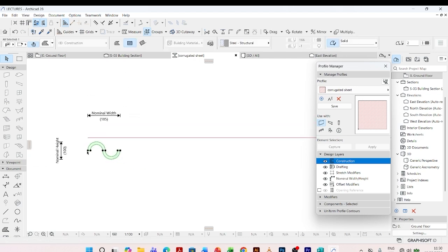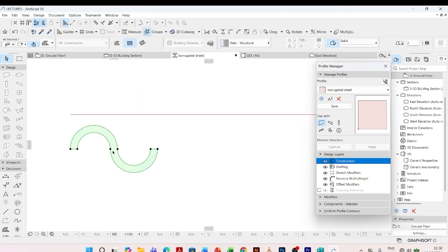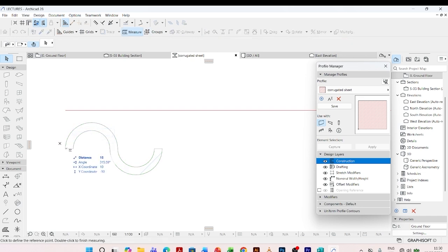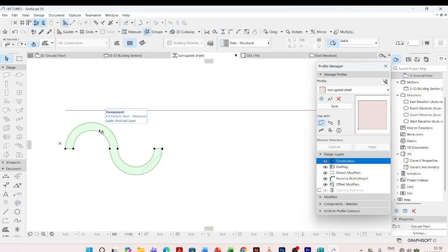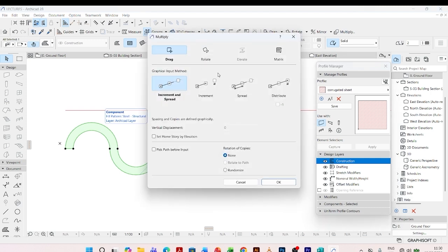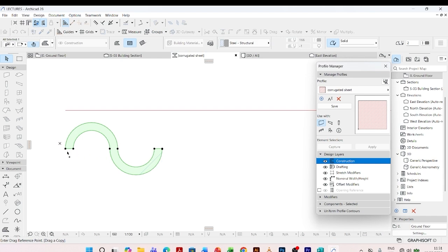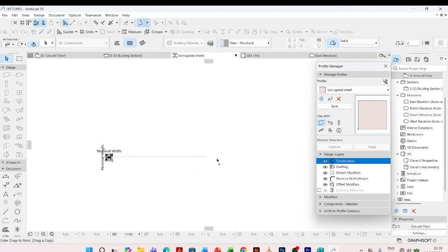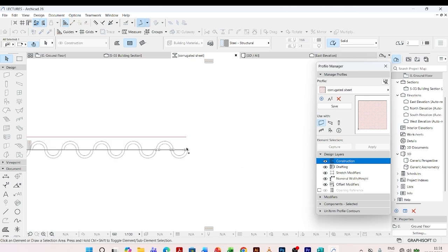So I'm going to spread this all the way 8.5, but I need to know what distance it is. Click on M on the keyboard. This is 185, so I'll click on it, then I'll type Ctrl U on the keyboard, and I simply come here and spread. I'll give it a distance of 185, the one we have measured, and I'll say OK. Spread this, I hold on to shift so that it keeps in a straight line up to somewhere here.